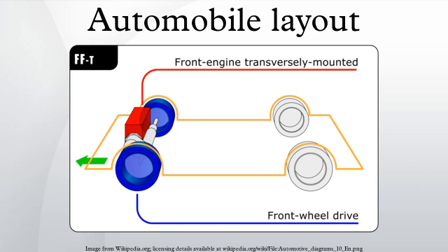Predictable handling characteristics. Front-wheel drive cars, with a front weight bias, tend to understeer at the limit, which is easier since it makes instinct correct in avoiding terminal oversteer, and less prone to result in fishtailing or a spin. A skilled driver can control the movement of the car even while skidding by steering, throttling and pulling the handbrake. It is easier to correct trailing throttle or trailing brake oversteer. The wheelbase can be extended without building a longer drive shaft.